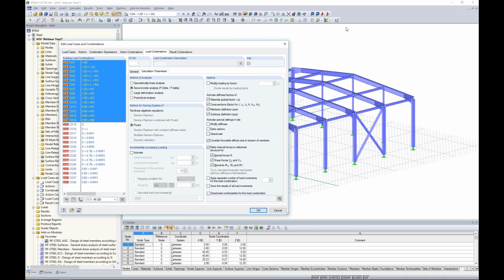So for one story, it really doesn't matter, but when you're getting into multiple levels, drift is not as easy as just taking a look at deformation of one height versus the other; you also need to take into consideration the different height levels. We don't have a table for drift at the moment. That is something that we do plan to implement into the program. But quite honestly, it's not that hard to pull your drift information.